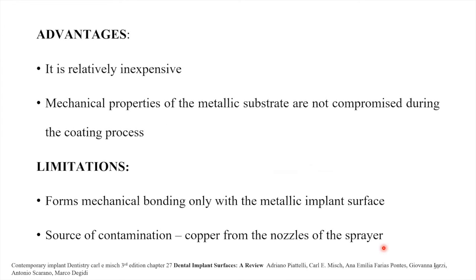The advantage is it is relatively inexpensive. The mechanical properties of the metallic substrate are not compromised during the coating process. The limitations could be it forms a mechanical bonding only with the metallic implant surface, and there can be sources of contamination from the nozzle of the sprayer.